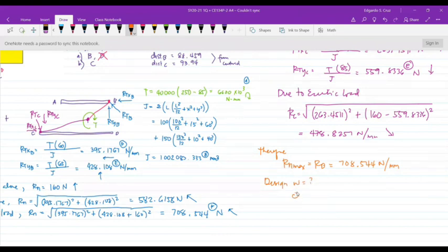Okay. Diba, sabi natin, the design strength should be greater than or equal to the ultimate. Okay, since the given load in the connection is already factored, P sub U na yung given, it follows that yung RB na na-solve natin na to is already R sub U. Okay, ito na yung pinaka-ultimate. Ito na yung pinaka-RU natin. Okay, so ano yung phi? Phi is 0.75 for connection. Ano yung Rn natin? Diba yun yung shear strength, Fnw, times the area of the shear for weld should be greater than or equal to Ru. Okay. So 0.75.